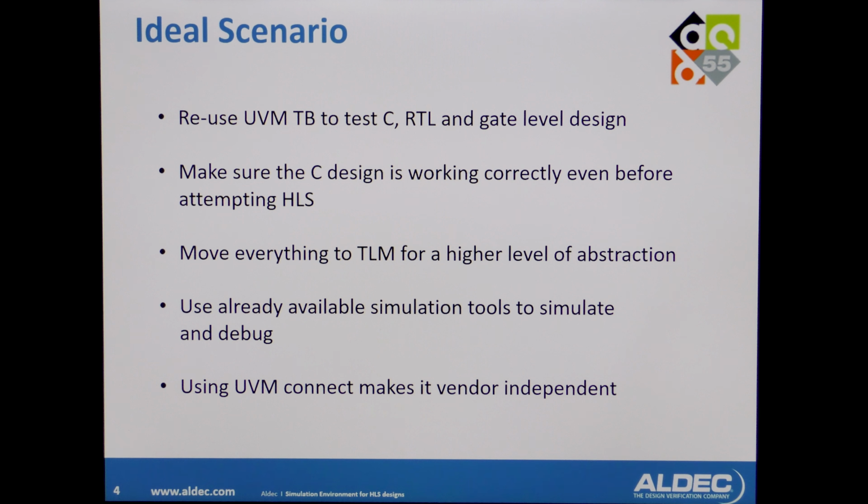In an ideal scenario, you would want to reuse your UVM test environment to make sure your C design is working correctly even before you attempt to run any kind of high-level synthesis. You want to move everything to a higher level of abstraction, so you can also use readily available simulation tools to simulate and debug.